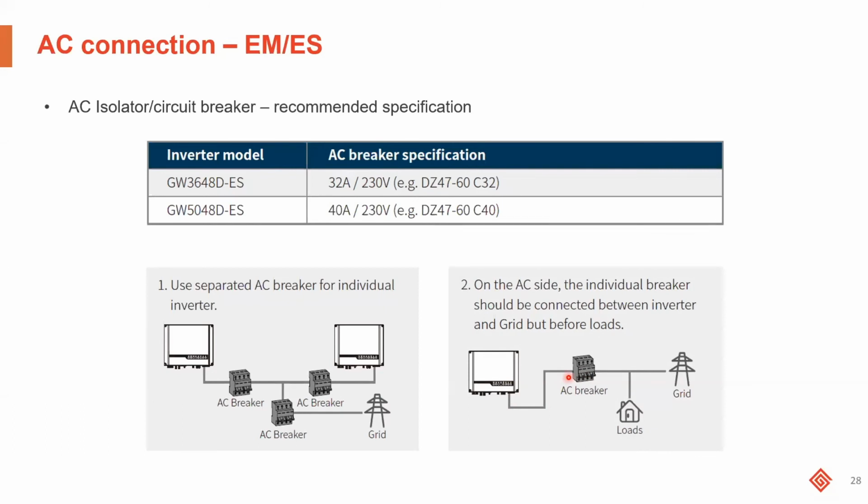So the AC breaker is there as an isolating point and to protect the cable. The AC breaker is not to protect any device within the system. It's mainly used to stop the cables from catching on fire.